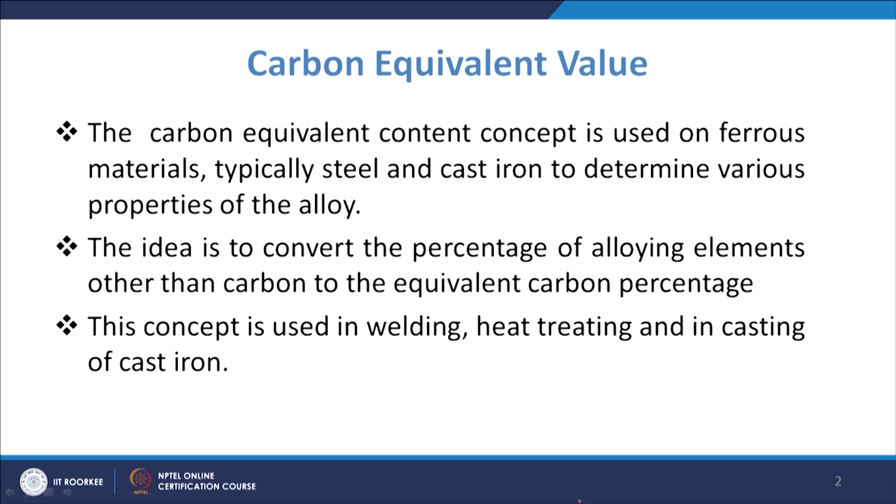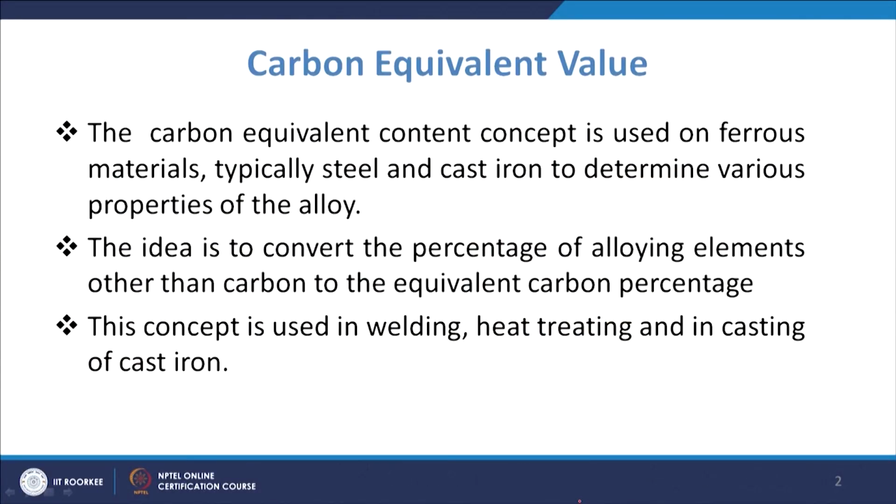As we know, when we talk about cast iron, we are talking about the eutectic composition. We will talk about how, even in cast iron, while casting, the carbon equivalent value comes into the picture, or even in welding. So, this concept is used in welding, heat treating and in casting of cast iron. While talking about the casting of cast iron components, this carbon equivalent value has a lot of significance.